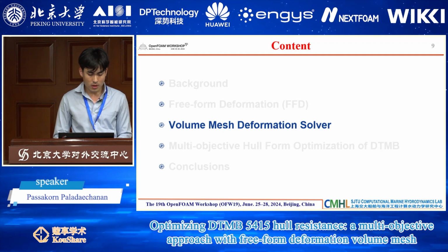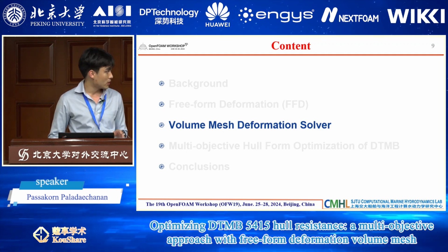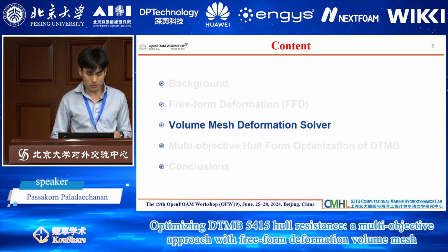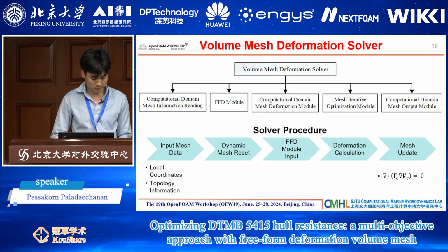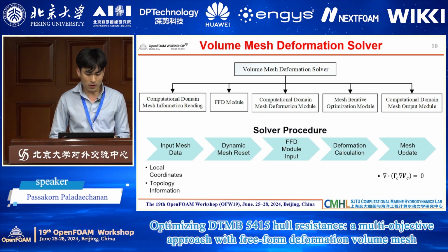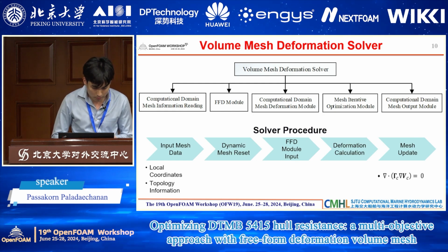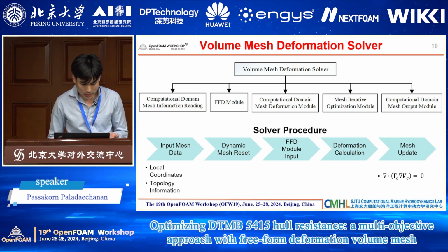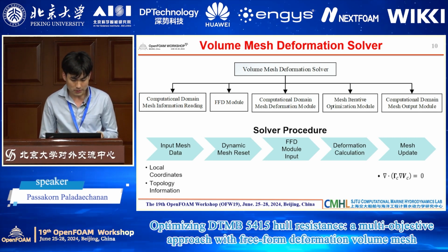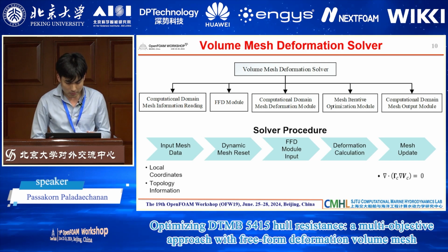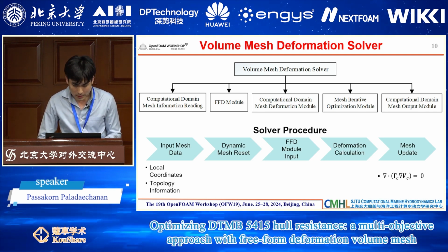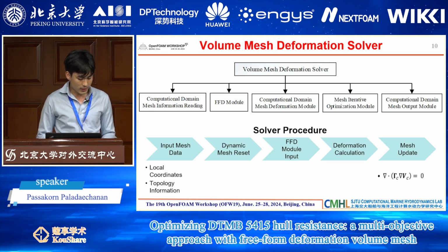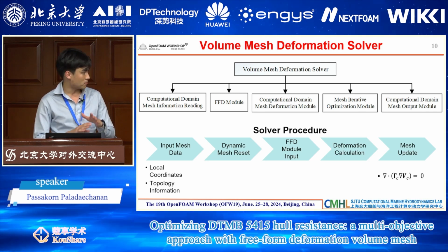About the volumetric deformation solver, we also apply this freeform deformation to this solver. This solver includes the computational domain mesh information reading and FFD module, computational domain mesh deformation module, mesh iterative optimization module, and computational domain mesh output module. The solver procedure: first, we need to read the coordinate and topology information of the structure boundary mesh.